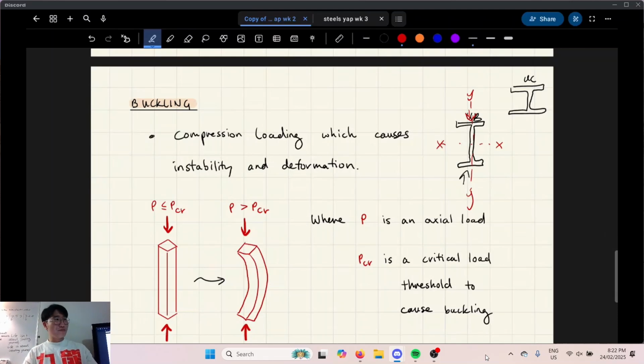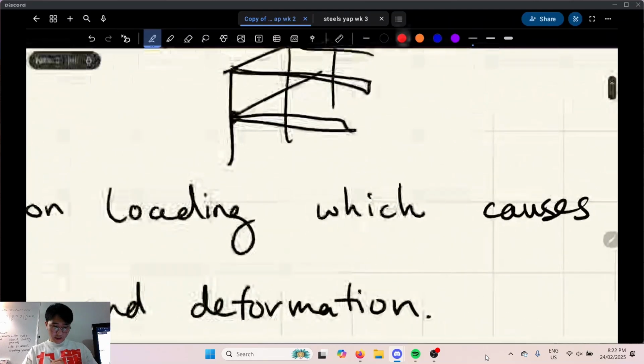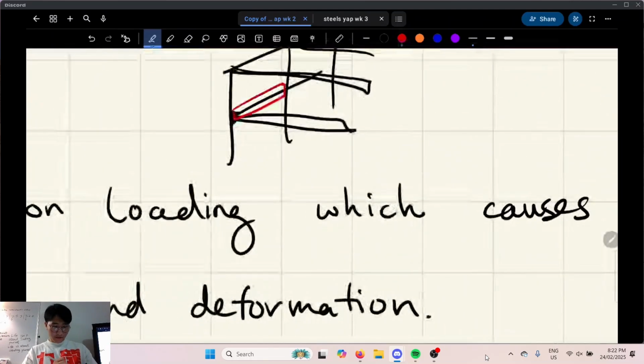But what kind of loads are you expecting beams to take? Dead load, pretty much gravity. You rarely expect beams to take much in terms of wind, because that's not what they're designed to do. On the exterior of a building, the big rafter frame, those are beams. The ones on the edge that receive a decent amount of wind load are usually box sections, hollow sections, because those are a little bit better in both directions. But these big ones are usually I-beams.